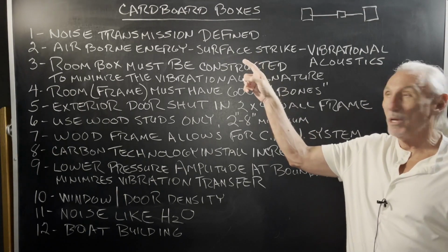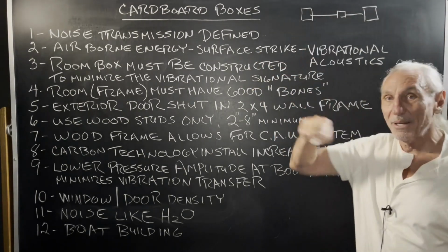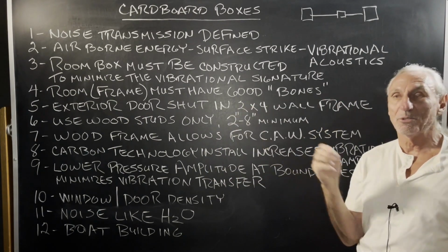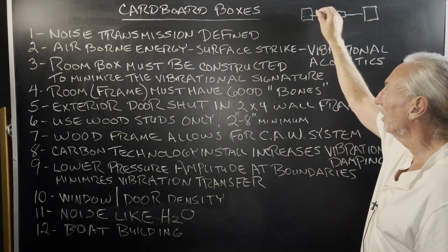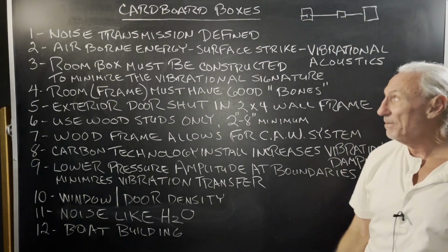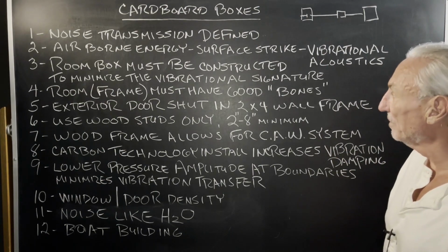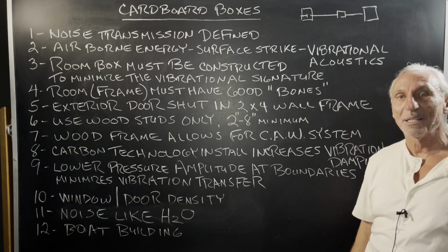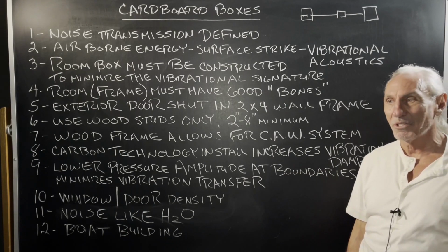And when we're dealing with noise, we're going from air energy, noise that's being transmitted through the air, striking a solid surface in our walls, and then entering our room. So it's vibrational acoustics that we have to manage. That's the science that we use. The room must be constructed in a way to minimize the vibrational signature.